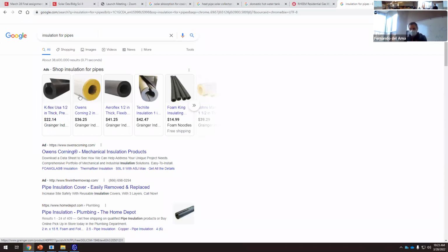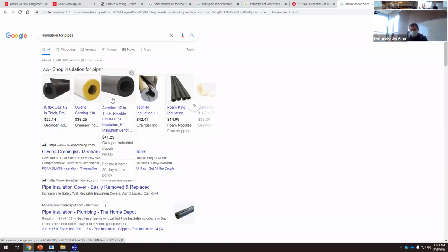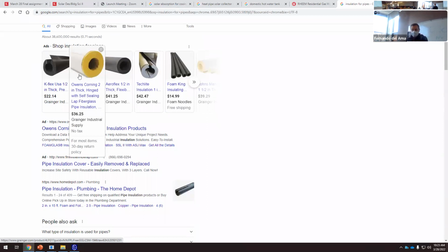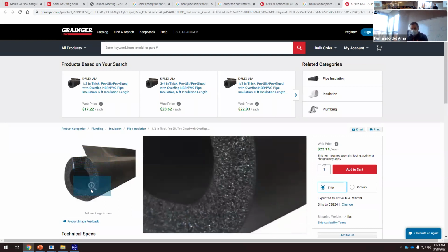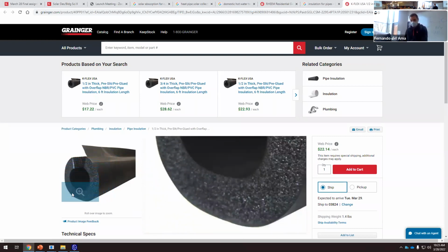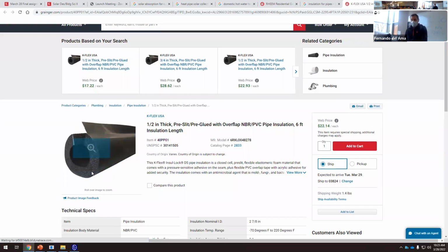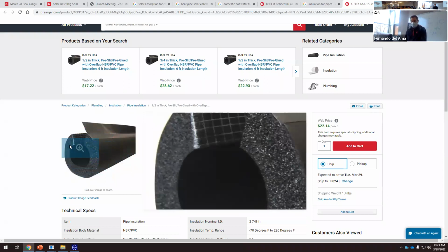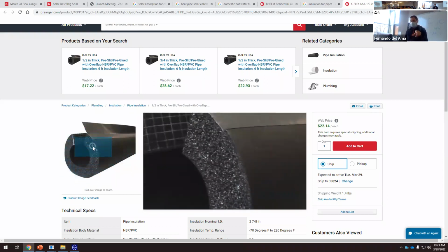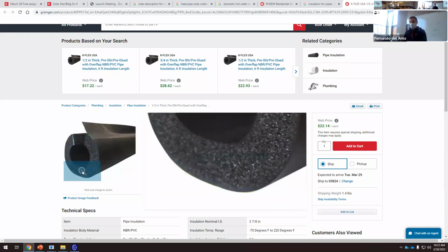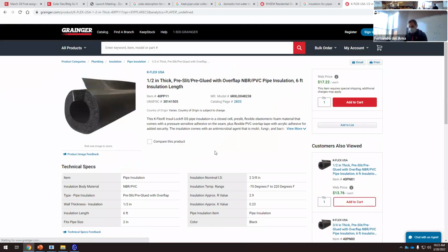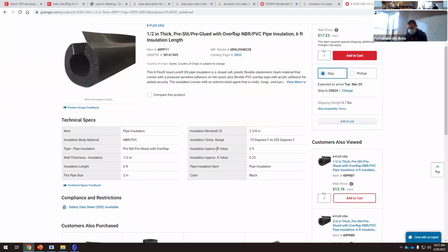We do. If you look at your boiler or something, usually the pipes are wrapped with this kind of element, okay, with thermal insulation like this. So again, this element will provide you with the UA value. The U value, the thickness of the thermal insulation, and the area is the perimeter of the pipe. It depends on the size of that circle. Okay, so again, if you look at this, at some point, we have the R value of this insulation, it's 2.9.